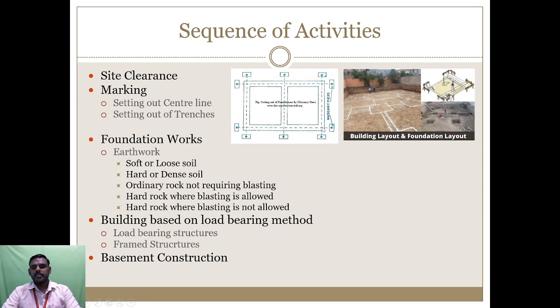Okay, when we are going for foundation, we have to know that the structure will be in proper alignment. Then we have to know whether it is at a right angle or not. That also, while marking, we have to verify based on the Pythagoras theorem. We have to maintain a right angle at all the corners. That verification is very much needed. Okay, next, nowadays a lot of people are going for framed structures.